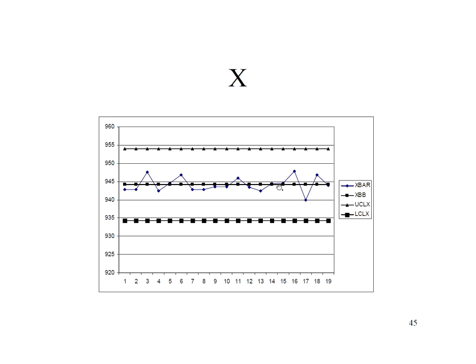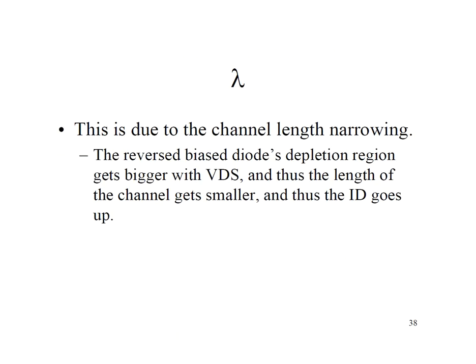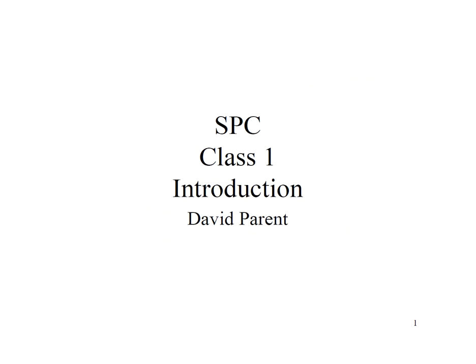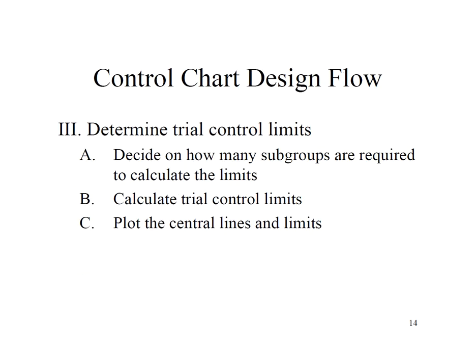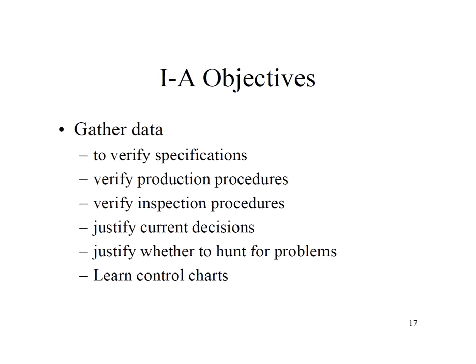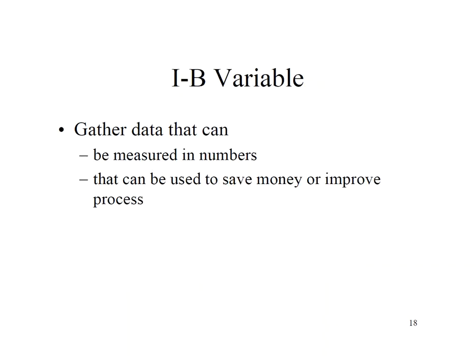Then sometimes it's based on the range, what's the difference, right? Sometimes based on the standard deviation, you get these upper and lower control limits. So there's rules that when you look at the points, as you plot things through, that will tell you whether you really have a problem or whether you don't. So that is a control chart, you're measuring something over time, right? That when you look at it, in another talk, it'll tell you